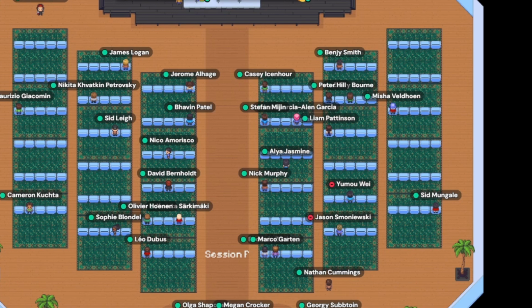But here, what we're doing in the simulation that I was showing, actually wanted to show since the video didn't work, is that we can directly use the multi-app system in MOOSE so that you have a main application that sends everything, runs the OpenMC for you automatically with the parameters that you gave it, and then directly takes the volumetric heating source and sends it to the rest of the MOOSE application. And you can send information like this both ways. So in that case, you don't need to handle the data transfer at all manually. It's all done within the multi-app system. Hopefully that, Luis, let me know if that wasn't clear enough.